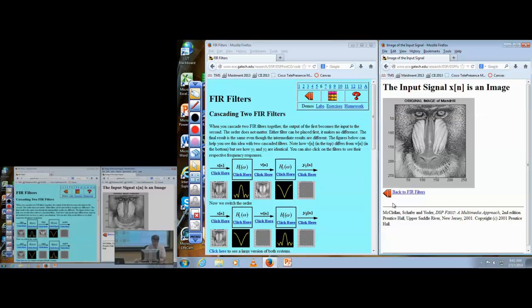As we go across the image, we'll see that in the nose and cheek area, we can see a black line followed by white, black line followed by white. Again, any transition from white to black is a high frequency transition, and also black to white as well. So what we see here in an image is that the high frequency content is representing both texture of the hair and lines in the face. So if we apply a low-pass filter, those features should blur out, and we'll see that they do. So the first step is to apply the averaging filter.